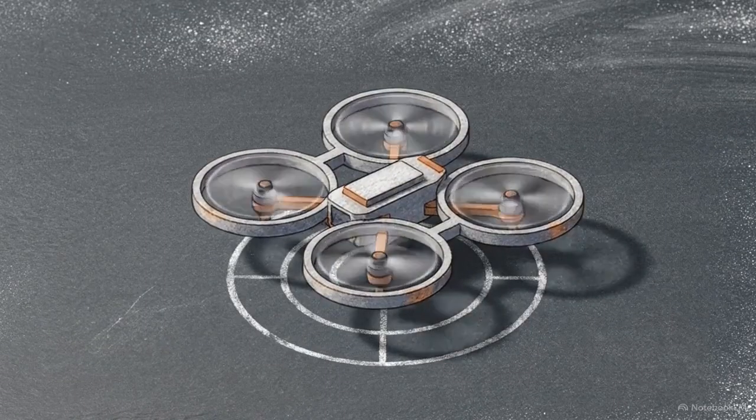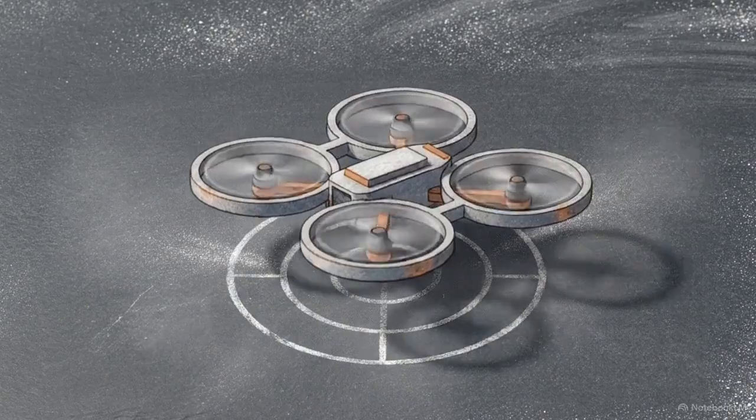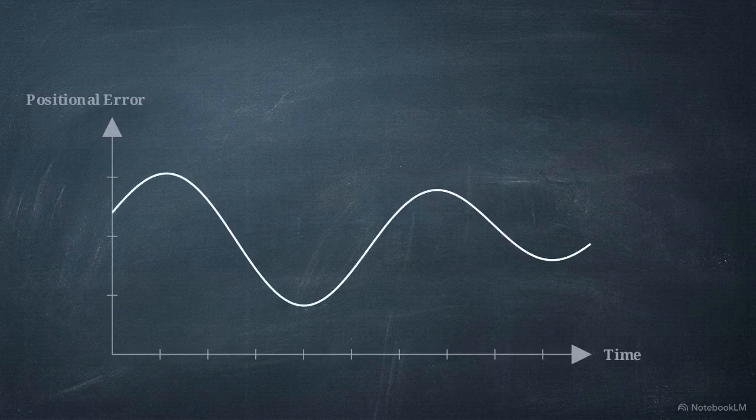If a hovering drone is pushed off course by a steady crosswind, the software has to recognize the drift and fight back. The flight controller handles this using the integral term of a PID controller. The algorithm constantly calculates the definite integral of the drone's positional error over time to force a correction against the steady drift.